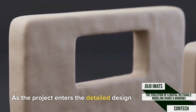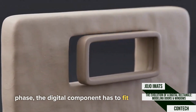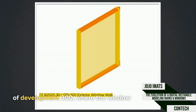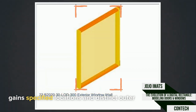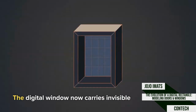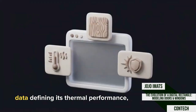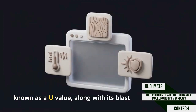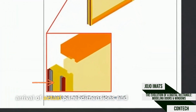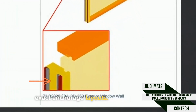As the project enters the detailed design phase, the digital component has to fit precisely into real structural openings. This rendering shows the upgrade to level of development 300, where the window gains specified locations and distinct outer geometry. The component is also getting smarter by absorbing non-graphic parameters. The digital window now carries invisible data defining its thermal performance, known as a U value, along with its blast resistance and aesthetic finish. This technical callout shows the highly advanced LOD 350 stage, revealing the arrival of actual panel dimensions and exact anchorage layouts.